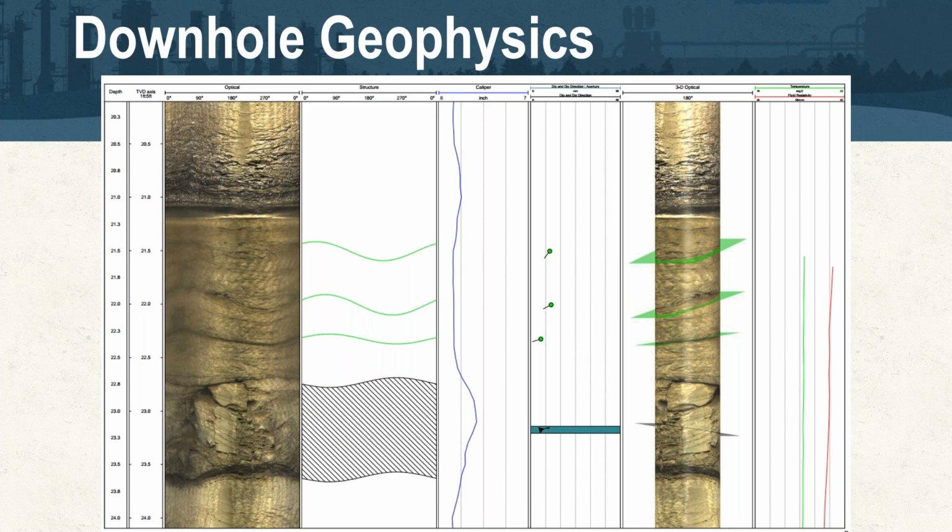And what we found that's really interesting and quite remarkable is that the injection tooling itself, or the injection methodology, cuts through the bentonite quite easily and can access those permeable zones within the formation that would otherwise be inaccessible, whether through traditional direct push due to early refusal, or off limits because the borehole integrity is too poor to utilize packer assemblies like we've talked about here.